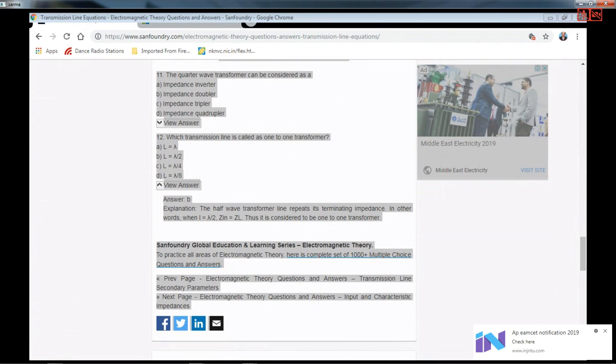Okay, so this mod gamma, as we see, is the reflected to incident voltage ratio amplitude-wise. It can have a minimum value of 0, because when there is no reflection, you get mod gamma as 0. And when there is complete reflection, that means the wave is not able to proceed into the load and completely gets reflected, you will have the reflected value same as the incident one, either in phase or opposite phase.